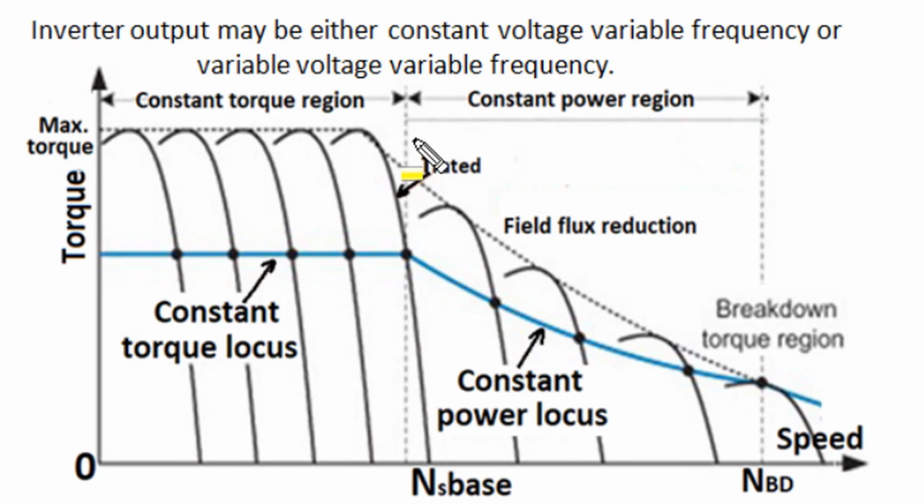When a rated frequency supply at rated voltage is given to the stator, the synchronous speed of the rotating magnetic field is at rated condition, and with a certain amount of slip, the motor operates at rated speed. Now, to reduce speed from rated speed, we can reduce supply frequency, and when supply frequency is reduced, we also reduce the applied voltage to the stator so as to maintain a constant voltage to frequency ratio.